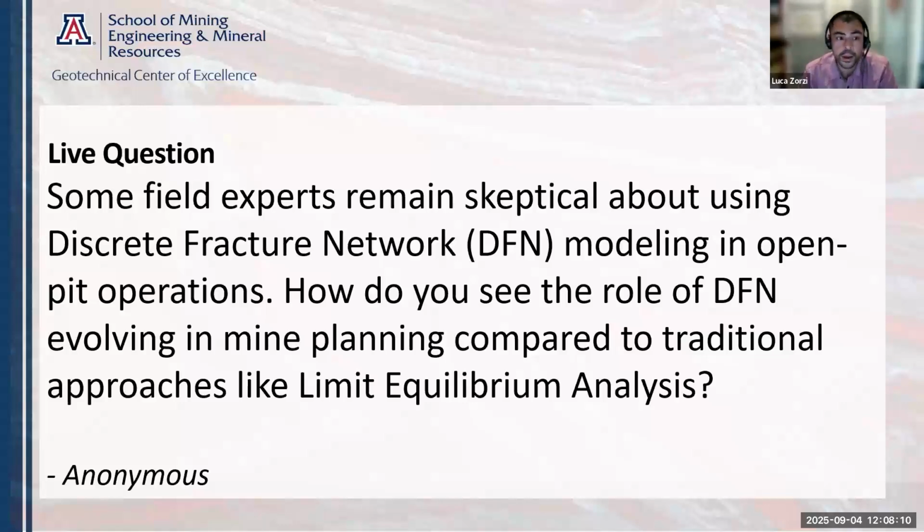It's evolving by AI, again. You increase the amount of the stochastic approach that you can use. And you can see even now other major companies like RockScience and right now even Itasca moving towards this. Instead of using ubiquitous jointing or limit equilibrium analysis, they're starting to say, okay, let's build a DFN and use that in our analysis instead of assuming ubiquitous continuous structures everywhere.